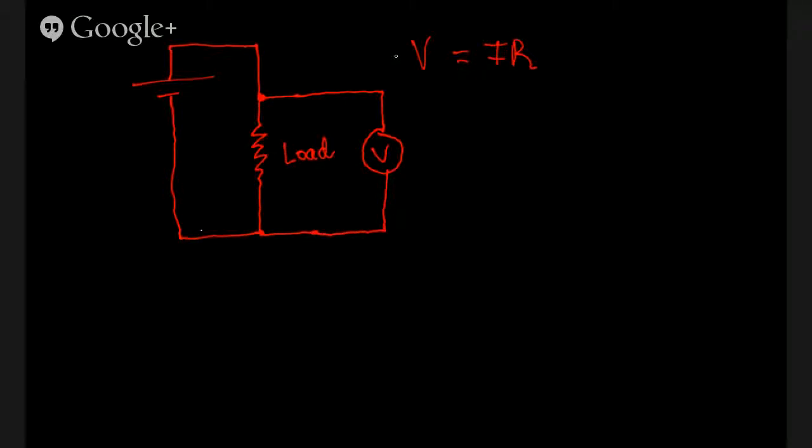All right. We can also measure current. So remember, counting electrons. We'll put our ammeter here. And let's say this is an unknown resistance. But we've measured a voltage of 100 volts here, and let's say 100 milliamps here. Pretty easy. Just plug it into our equation here.